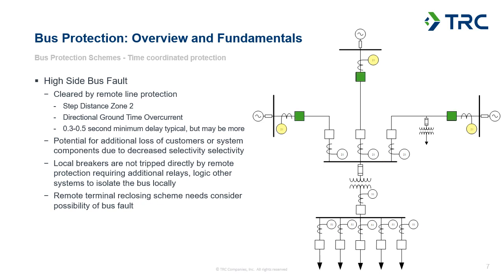When the relays time out and their zone 2 timer expires, they'll operate to trip their local breaker, the same way they would if they were tripping for a line fault. And you can see the 3 breakers here I've shown as opened up, and that would clear the bus fault and put the bus fault away. And that's, of course, assuming that the distribution system connected here is radial, so there's no fault sources or things feeding back up through the transformer.